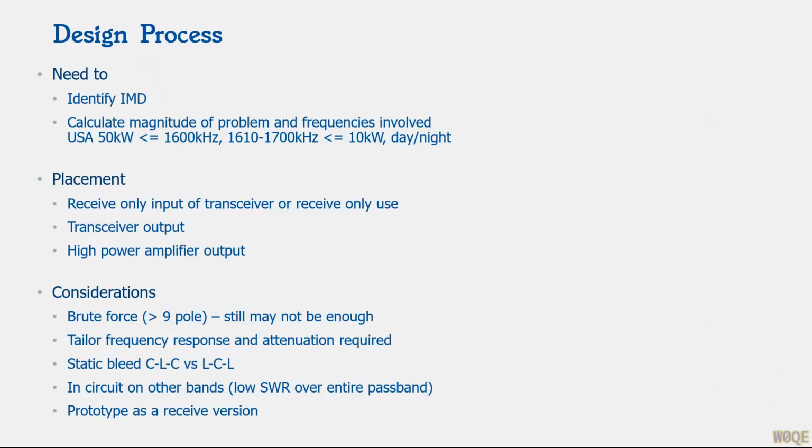The interference that we see from the AM radio stations, other than if they happen to be a harmonic and we hear them in a band, is due to a process called intermodulation distortion, or IMD. Intermodulation distortion occurs anytime you have a circuit which is nonlinear and you have more than one frequency applied to that circuit. There will be mixing products involved, and the mixing products will produce signals, we can call them phantom signals, which occur at a frequency which really doesn't exist other than inside the radio. However, you hear them on the output of your radio.